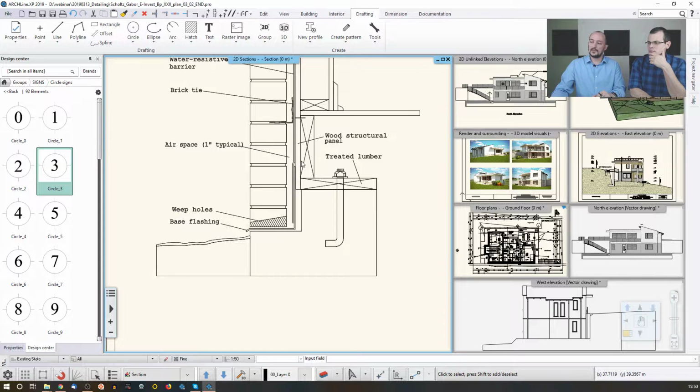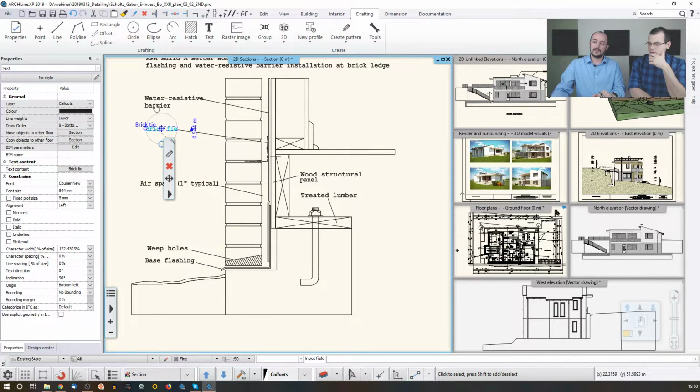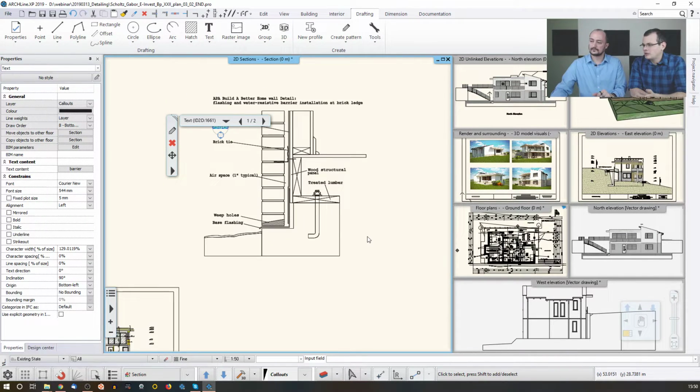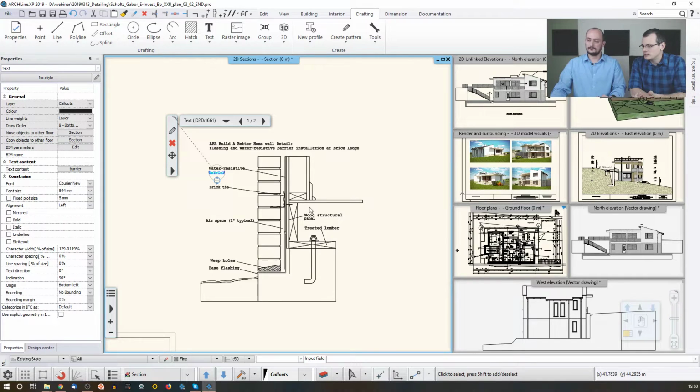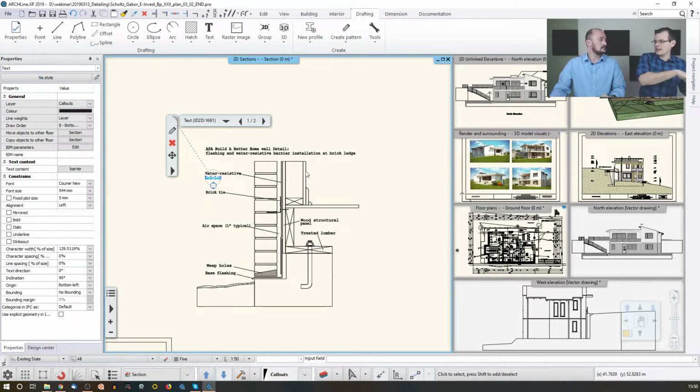But the whole point is that this is a drawing that I can customize. I can add hatchings. I can just remove parts, or I can just shrink it, make a copy, and paste it into my drawing and stitch it together with my own drawings. I'll show you two examples. One is how you add a customized hatch pattern to it, and the other one is how you make this into a library element for later use. So you don't have to manually drag them in every time, but you can add it to your library.